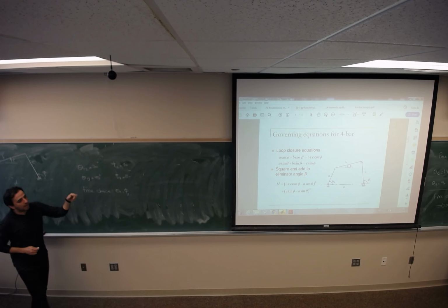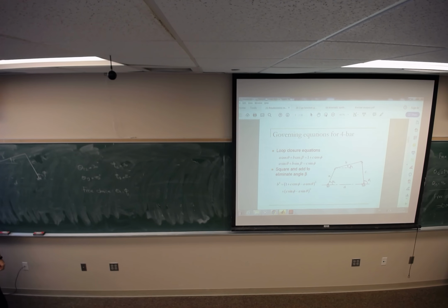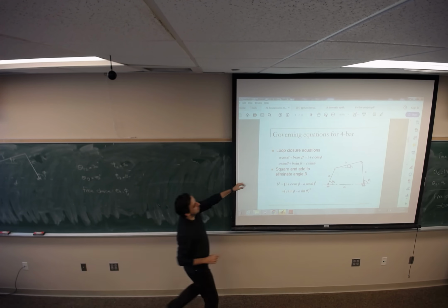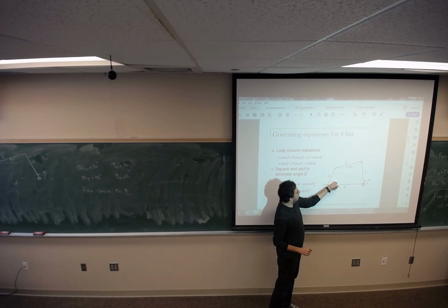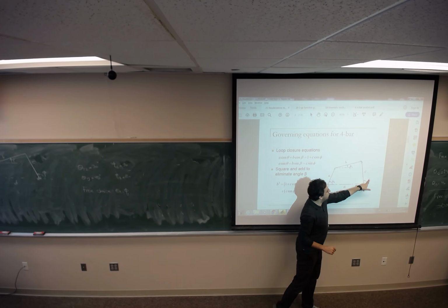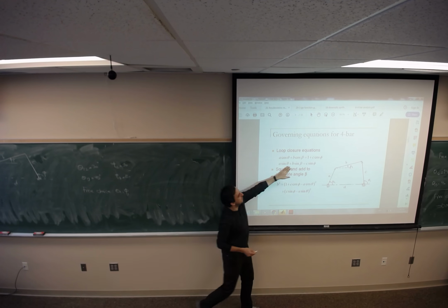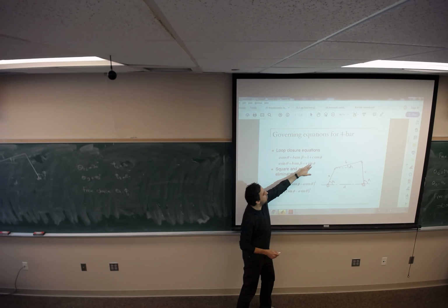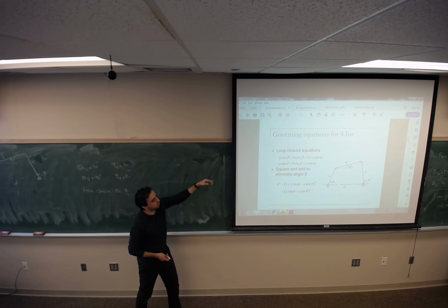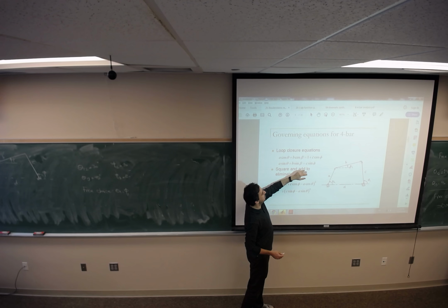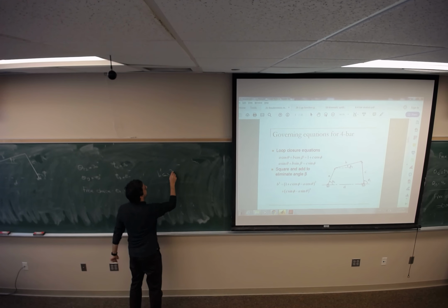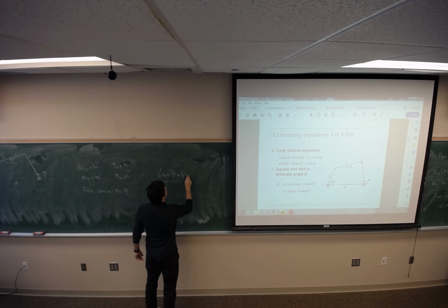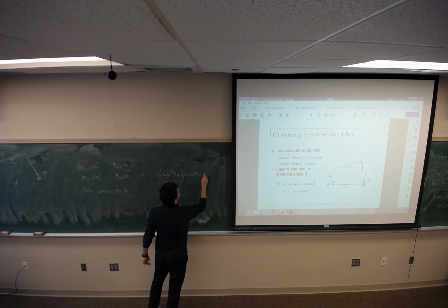We have seen this in the motion analysis, or displacement analysis, for a four-bar mechanism. In that problem, we are given theta and solving for beta and phi, if you remember. What we did was try to get rid of either beta or phi, solve for the other one, and go back to these two equations. So if you want to get rid of beta, you move the other terms to the right side and square: B square cosine square of beta equals 1 plus C cosine of phi minus A cosine of theta, squared.